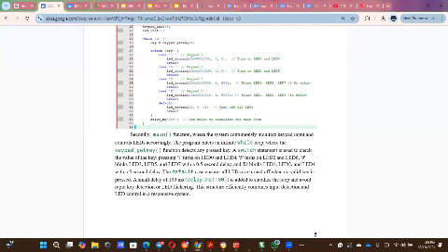When we press 5, it turns on LED 2 and also LED 6. When we press 9, it blinks LED 3, LED 5, and LED 7 with a 0.5 second delay. And when we press D, it blinks LED 1, LED 2, and LED 4 with a 5-second delay. And this case ensures all LEDs are turned off.